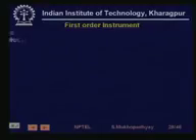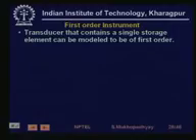On the other hand, there are some kinds of instruments where if the input changes suddenly, the output cannot change suddenly. The output takes some time to rise. For example, let's say temperature measuring instruments, for example, a thermocouple. Wherever it is making the measurement of the temperature, maybe it's steam, the bare thermocouple is actually not inserted into the steam, because that will damage the sensor. It will degrade fast. So it is actually put inside a tube, which is called a thermo well. It's a tube, and inside that you have the thermocouple.